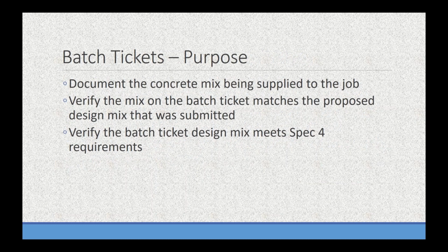We use the batch ticket to verify the mix. Travis talked about the pre-reviewed mix designs that we keep on the Appleton Tech Center website. So we'll want to verify that the batch ticket mix meets what they're telling us 7 days in advance that they're going to use. And then lastly, we'll use the batch ticket to check to make sure that all the other design requirements of Spec 4 are met.